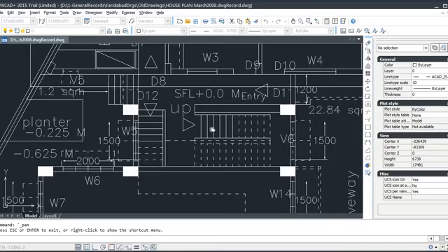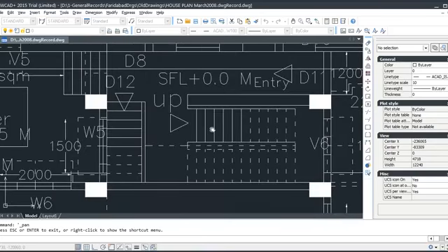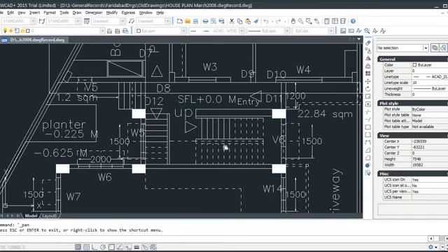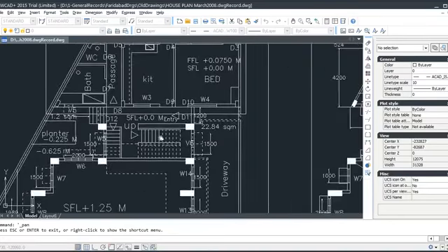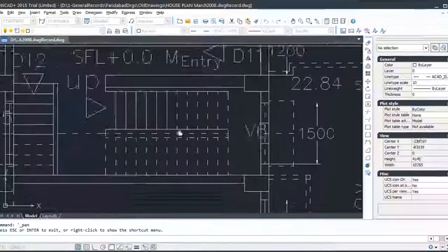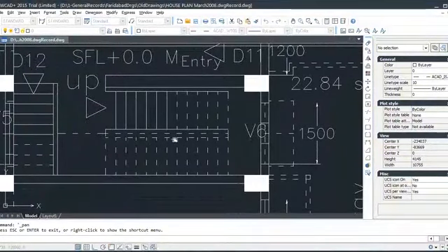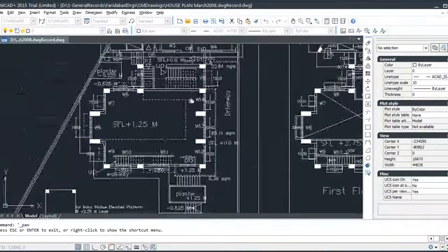In public buildings, it's 100 mm. They don't want people to use 150 mm or 200 mm because it's a public place. In private buildings, it is 125 mm. It can be 150 mm. It's not the case that you have to take 200 mm, you get tired in that. So what I mean to say is, a stair is very difficult to design, because the stair slab is inclined everywhere.